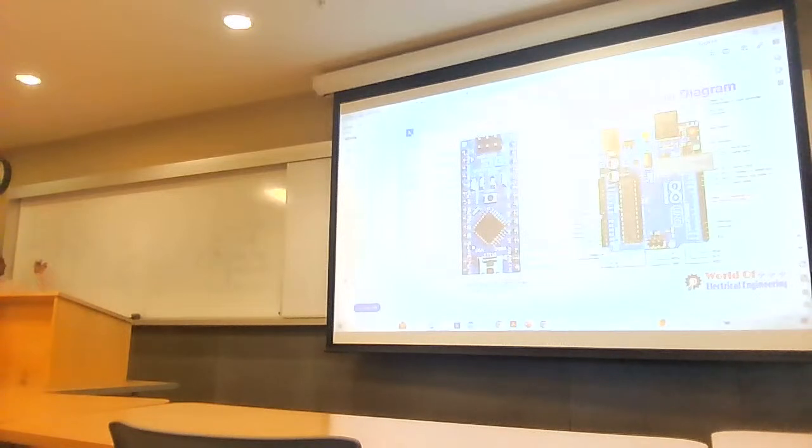So the job of this PFD is to find any phase difference between the reference and the feedback. Forget about whatever the feedback is. The job of this circuit is that it determines whether there is any phase difference or not, and whether there is any frequency difference or not. Let's say I am designing this VCO for 2.8 gigahertz, and if it changes from 2.8 gigahertz to 3 gigahertz, then this circuit determines there is a change, it plays a role, and then it will come back again to 2.8 gigahertz.